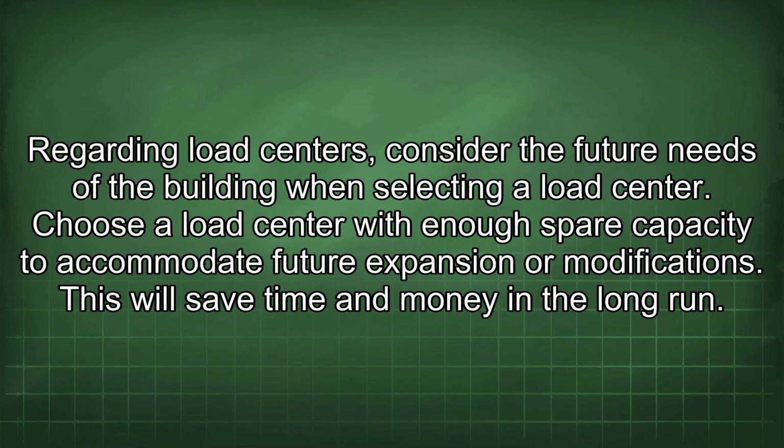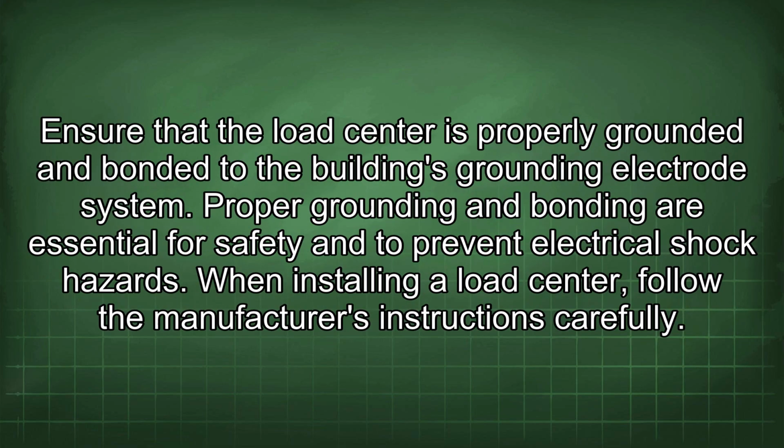Regarding load centers, consider the future needs of the building when selecting a load center. Choose a load center with enough spare capacity to accommodate future expansion or modifications. This will save time and money in the long run. Ensure that the load center is properly grounded and bonded to the building's grounding electrode system. Proper grounding and bonding are essential for safety and to prevent electrical shock hazards.